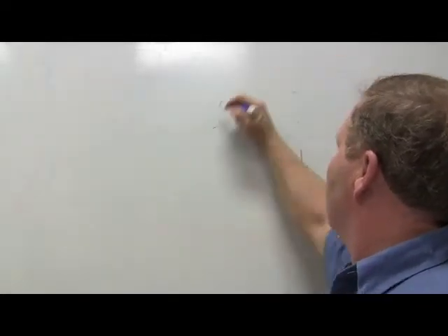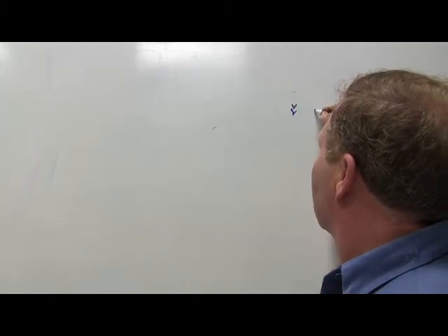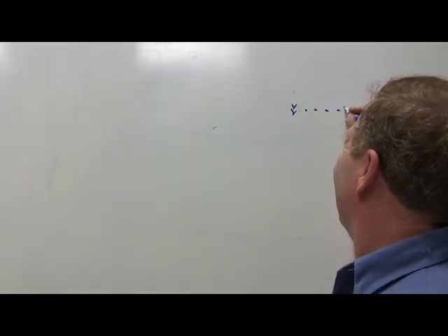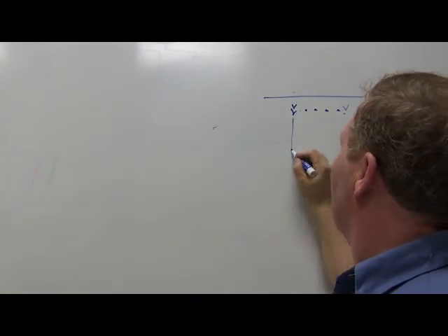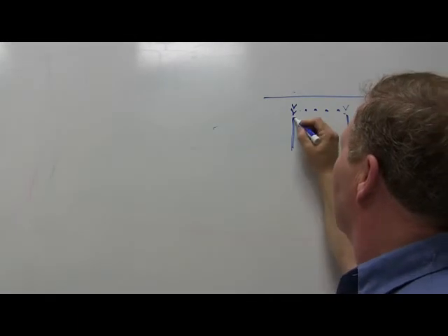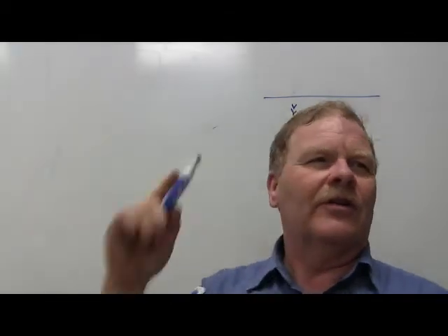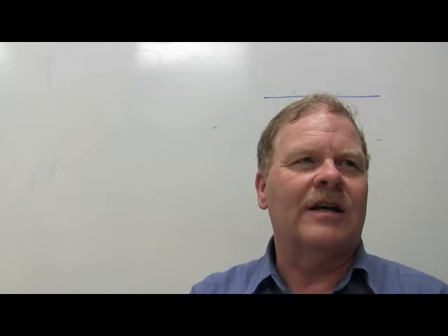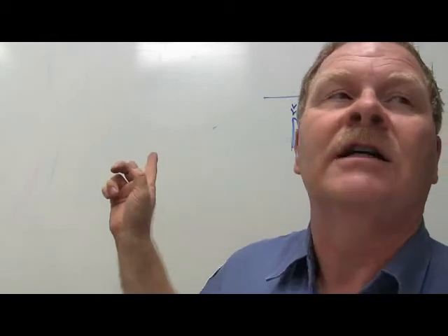You've also seen a connector on the wiring schematic. Like you've got a box here, and you've got wires coming in here. And you may see a wire coming out of there, a wire coming out of there, and then you'll also see one coming out there. That means both of those are hooked to the same terminal in that connector. They're making a junction point of that connector instead of soldering them together somewhere else. Now the good part about that is, if you've got them this way, you know where that junction is.